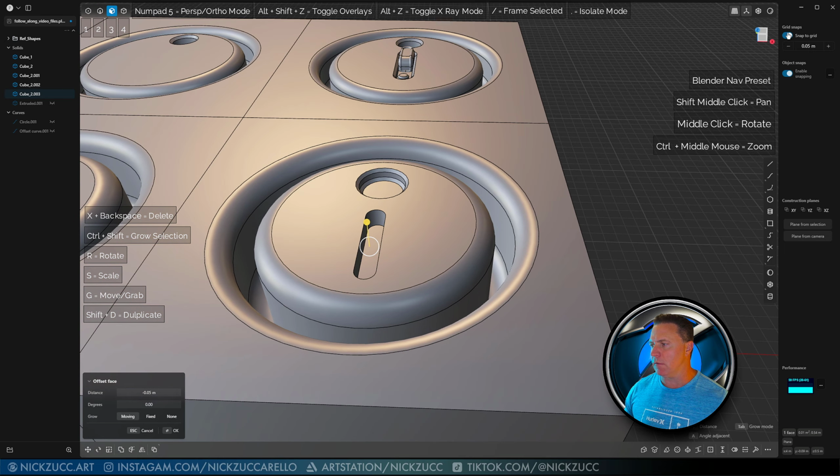Now we could use the trim tool and just trim away that part of the curve. And then if I've done this correctly, I should be able to tap 2 and get out of this trim tool. So right click on there. I'll select this, this, and tap J to join that. And if this works, you should see that join all into one curve.